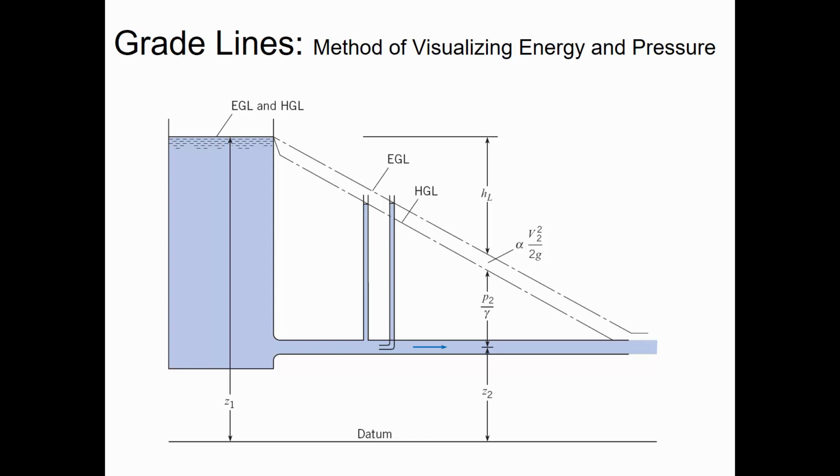But when the water starts to enter this pipe, energy is changing a little bit. Because as the water approaches that pipe, it's speeding up. It's getting velocity, whereas in most of the tank, the water has no velocity. In the immediate vicinity of the pipe, the water is accelerating in towards that pipe. And so if you're gaining some velocity, then that means the energy has to come from somewhere. And it's a localized reduction in pressure.